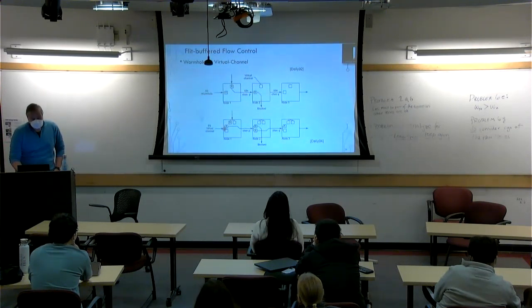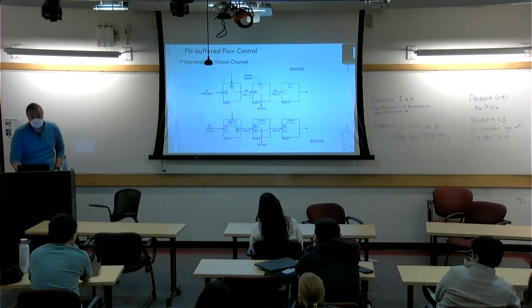Now, if you have virtual channels, you can do allocations from the same input port based on where they're going. So pick which one you want, right? Then you can route, for example, in this case, you know that this one is blocked, but this one is free to go to this other channel. So it will free up this buffer so that this whole path can advance and you can leverage this channel over here. It was idle, and now it's utilized because some other flow can use it.